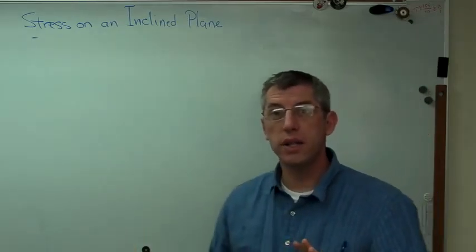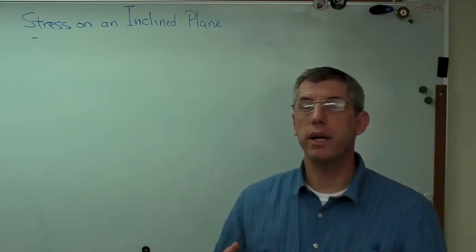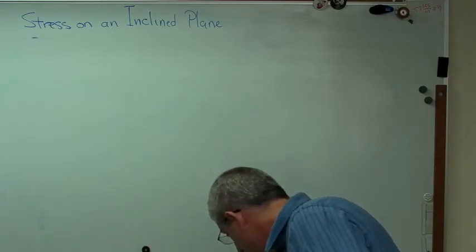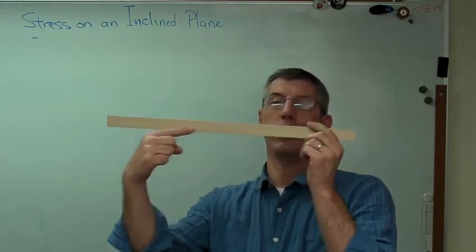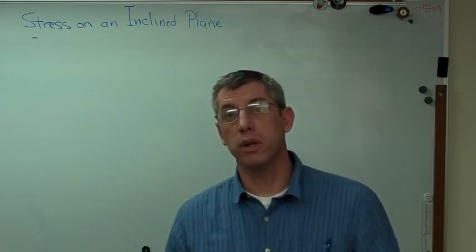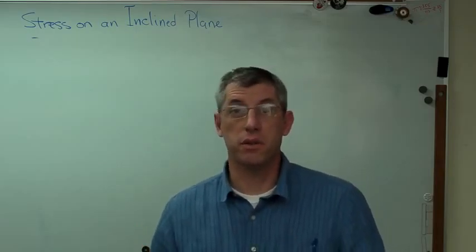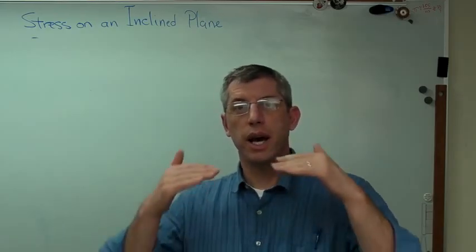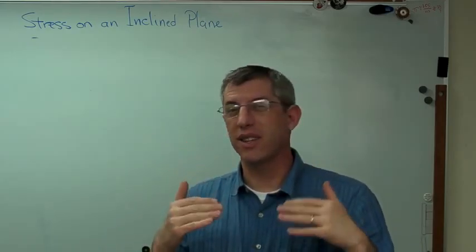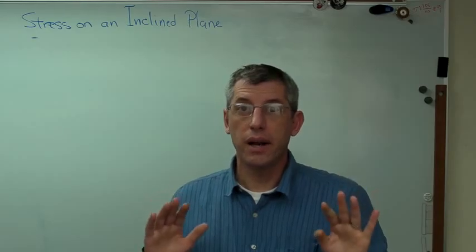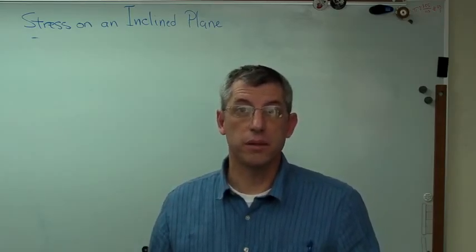So stress is directional. We tend to measure strain or calculate stress depending on whatever coordinate systems are convenient. So if I take my little ruler here, it makes good sense to put one of the axes going down that way and another one going this way. But there's no reason to think that just because I pick a set of axes that are convenient, the maximum stress will lay on that convenient axis. It could be something else. It's probably something else. So that's why we want to know Mohr's circle, and that's why we want to figure out stresses at some angle to a chosen axis. The axis we choose is a lot of times just for mathematical convenience, not necessarily for a good physical reason. All right?